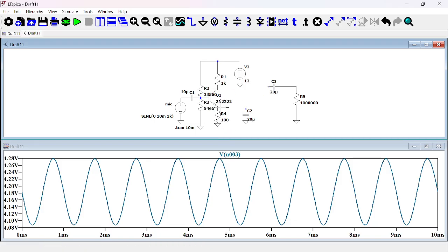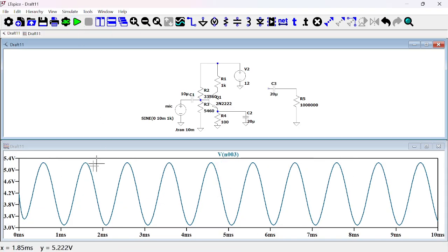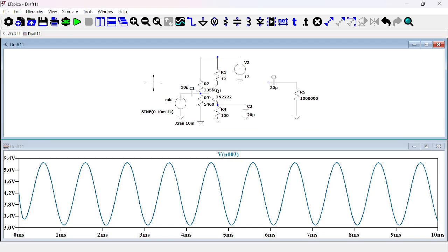We saw that bringing in the emitter resistor improved stability, so our bias error was fixed, but then the gain was reduced. By putting a bypass capacitor here, the AC signal will bypass the emitter resistor, which will improve our gain. And we are going to decouple our small signal AC output from the operating point DC fixed output.